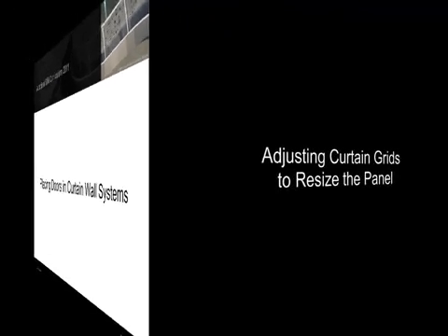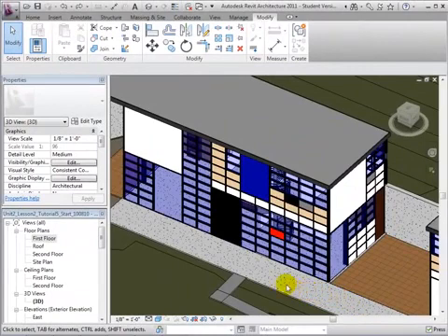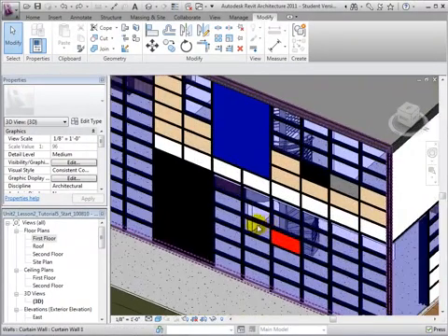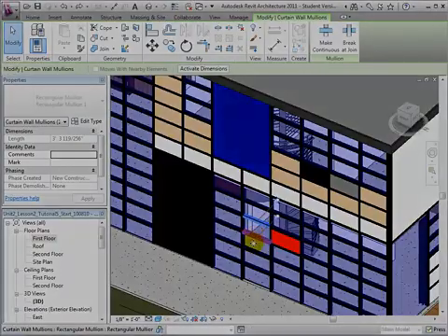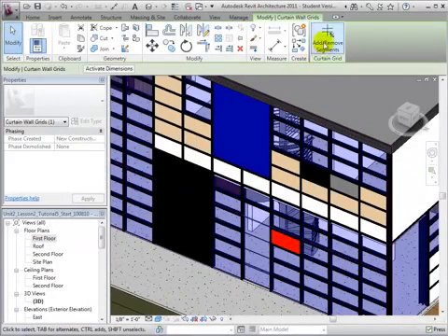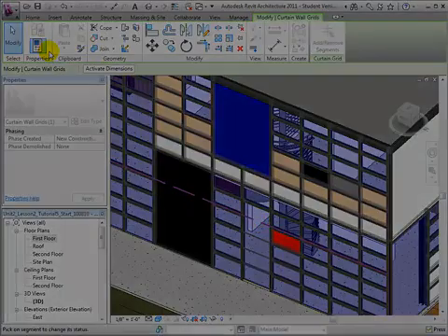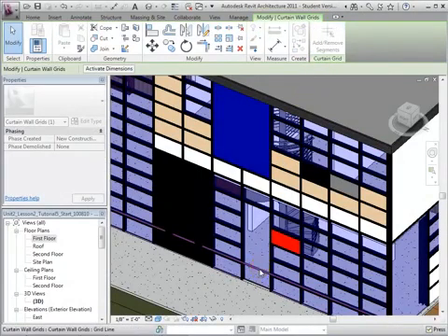We can place doors and curtain walls by replacing a panel type. Before doing this, we must first create a panel with appropriate door dimensions. First, let's delete the mullions by selecting them, unpinning them, and finally deleting them. Next, we must delete the grid line segments by selecting a grid line and using the Add Remove Segments tool. Once we have removed the desired mullions and grid line segments, we are left with a door-sized panel that we can turn into a door.